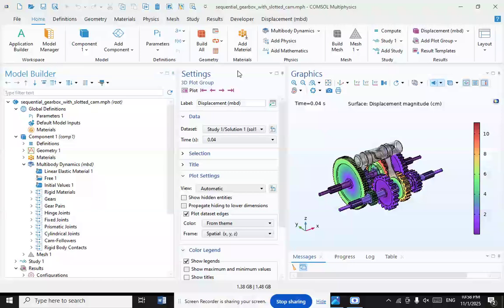When the driver selects a gear, the dog clutch for that gear is engaged via the gear selector rods, locking the transmission's output shaft to a particular gear set. This means that the output shaft rotates at the same speed as the selected gear, thus determining the gear ratio of the transmission. The dog clutch is a sliding selector mechanism that sits around the output shaft.